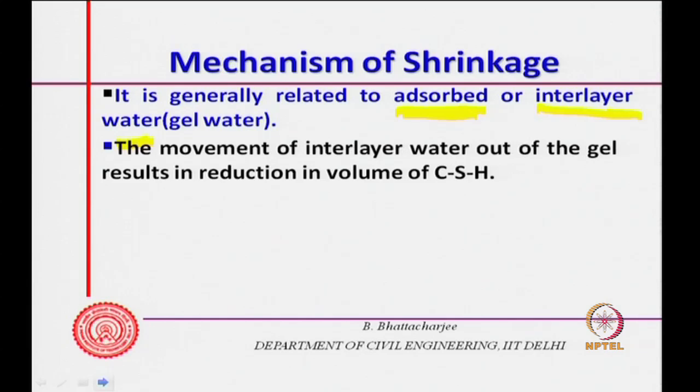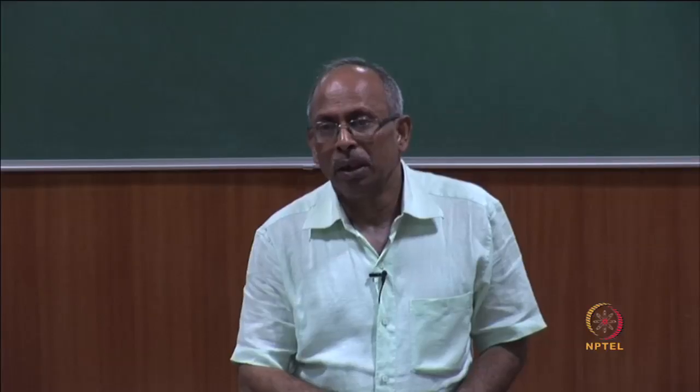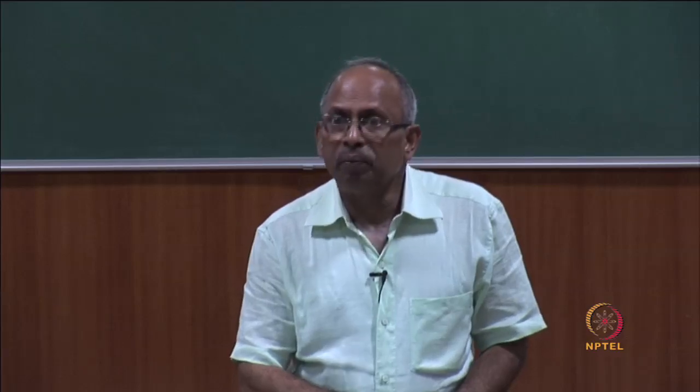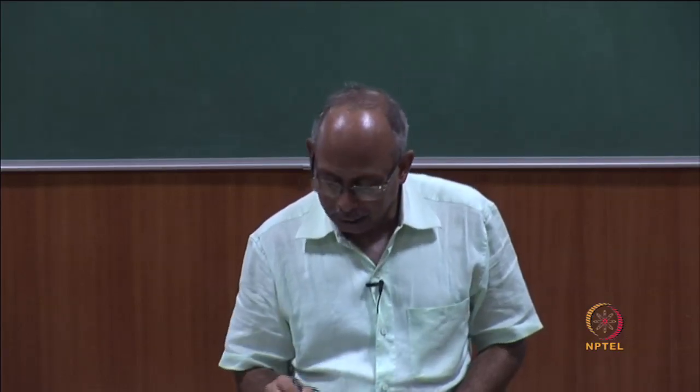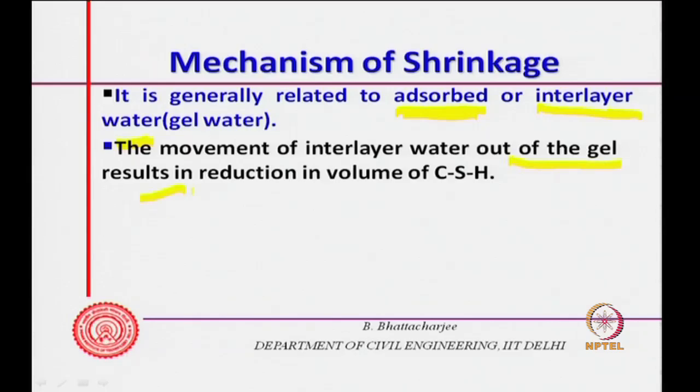Movement of this water, the gel water, the interlayer water, out of the gel results in reduction in volume of CSH, the calcium silicate hydrates. So, it actually results in reduction in the volume of the CSH gel.